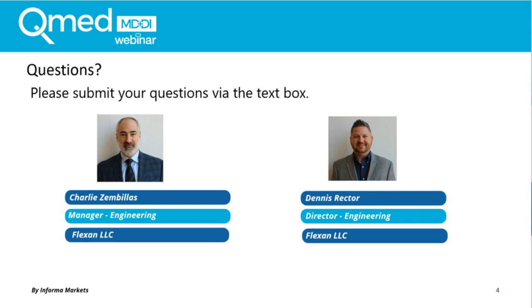All right, and we'll move on to another one here. What sterilization disinfection methods are best compatible for doing so? We mentioned gamma, but what about, it says EO. Maybe they're just shortening it. Yeah, it's ethylene oxide. Ethylene oxide is compatible with silicone. Most customers evaluate the residuals, but generally silicone is very good with EO residuals. The difference is that EO doesn't change the silicone dimensionally like gamma does.